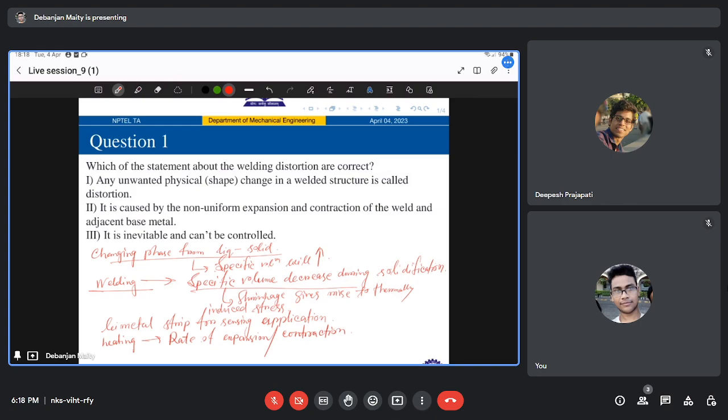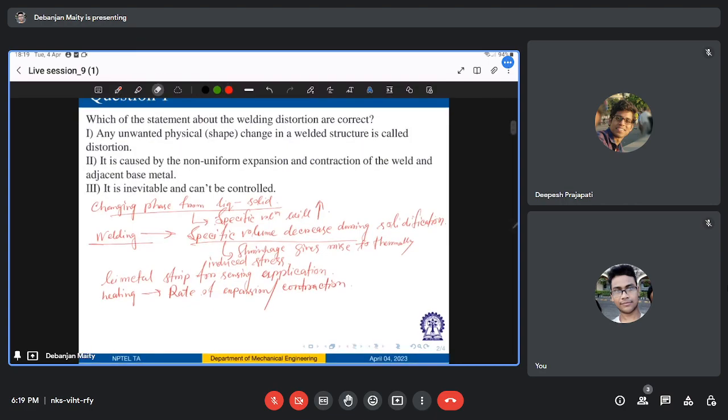So these are some basic ideas of how your residual stress can happen because of mismatch in coefficient of thermal expansion, because of some thermal gradient induced stress, those things. And this is how distortion and residual stress might arise from this same applied temperature range. So if you see, when stresses can cause, let us try to draw some figure here. Then let me explain the thing.